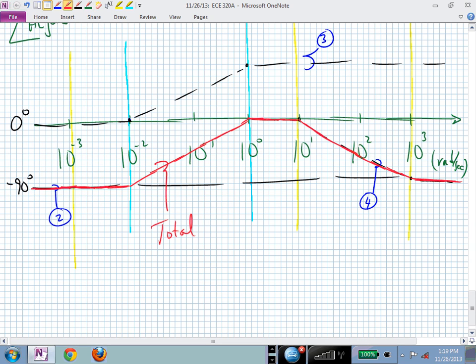You can identify the frequency of that sine and cosine and then go to these plots and say what your magnitude and angle are going to be at that particular frequency. So if you have 5 dominant or main modes in your periodic waveform, you can figure out what your output's going to be from this system. Yes? No? This is where we need to be going.